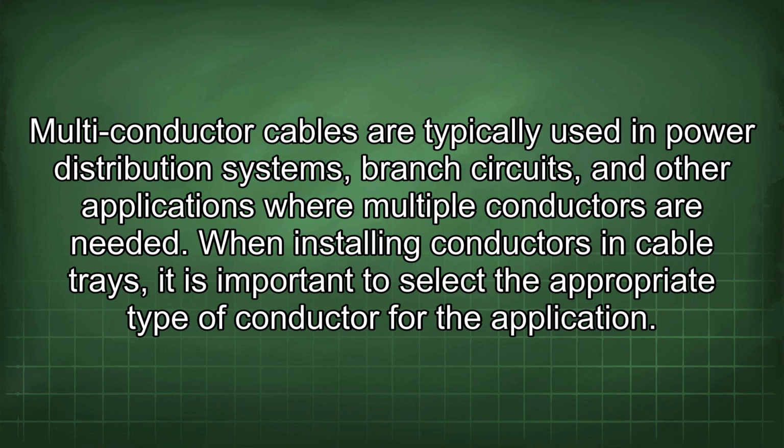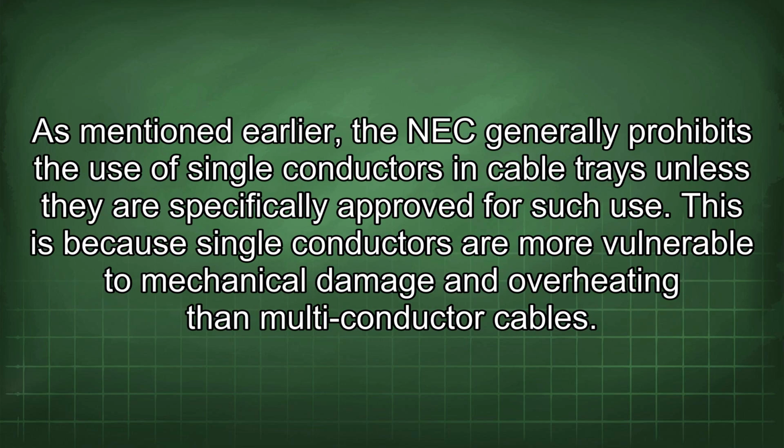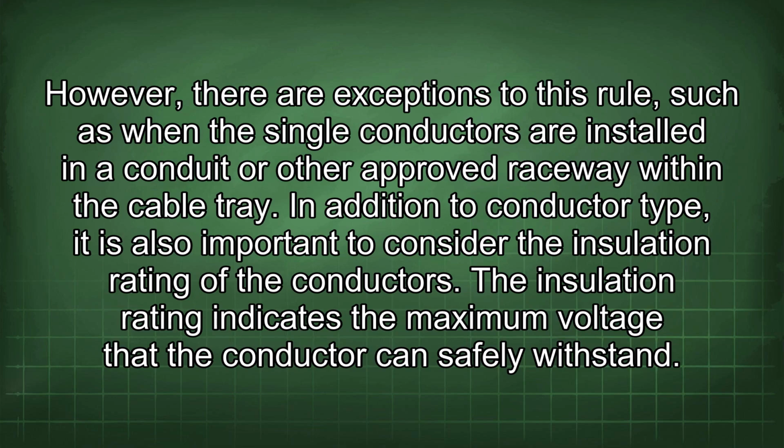When installing conductors in cable trays, it is important to select the appropriate type of conductor for the application. As mentioned earlier, the NEC generally prohibits the use of single conductors in cable trays unless they are specifically approved for such use. This is because single conductors are more vulnerable to mechanical damage and overheating than multi-conductor cables. However, there are exceptions to this rule, such as when the single conductors are installed in a conduit or other approved raceway within the cable tray.